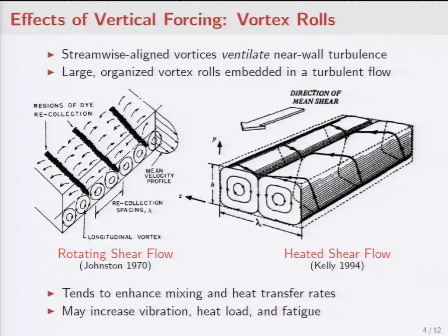If there are these vortex rolls that are taking the hot fluid above the wall and bringing it near the wall, then that can cause the blades to become scoured or melt and have patches like that occur. But you can also use film cooling, where you effectively generate streamwise vortices near the wall rather than in the large-scale flow, where cool flow is injected along the wall to counteract that effect.